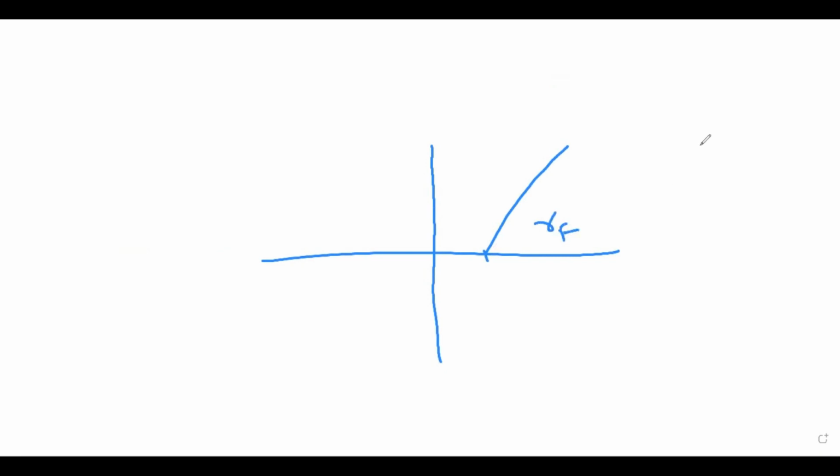The equivalent circuit of this is a voltage source with the forward resistance. This means a diode can be replaced by a voltage source and a resistance in the linear piecewise approximation. So this is about the diode approximations.